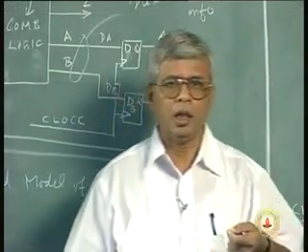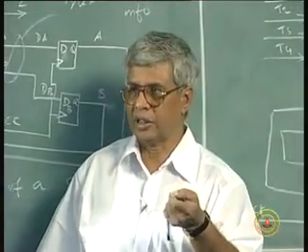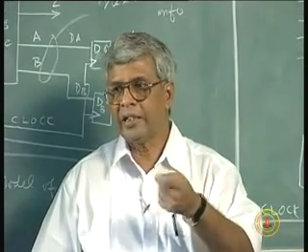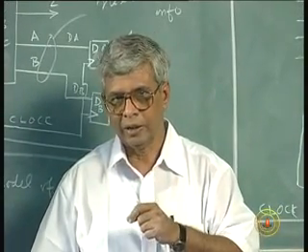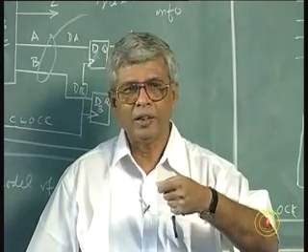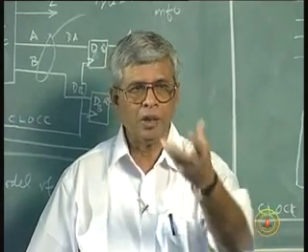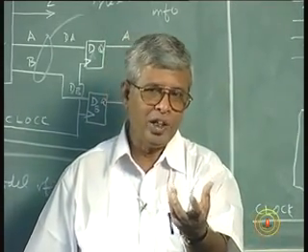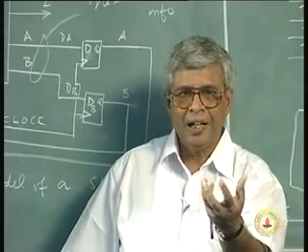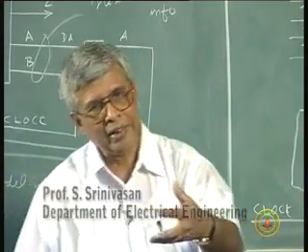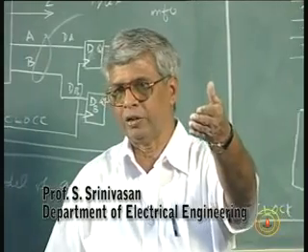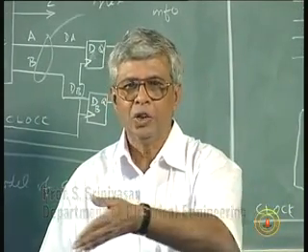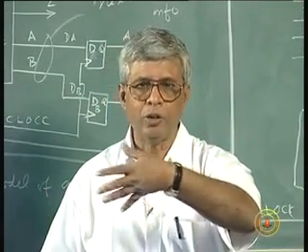So this is called a synchronous sequential circuit. In an asynchronous sequential circuit, there will be no clock to steer. Some events will drive the next state. Suppose I am in a present state, you can define a particular event to happen, and that event will take it to the next state, and you define another event to happen, that will steer to the next state, and so forth. That is a little more difficult to analyze as well as design. We will not do it now.